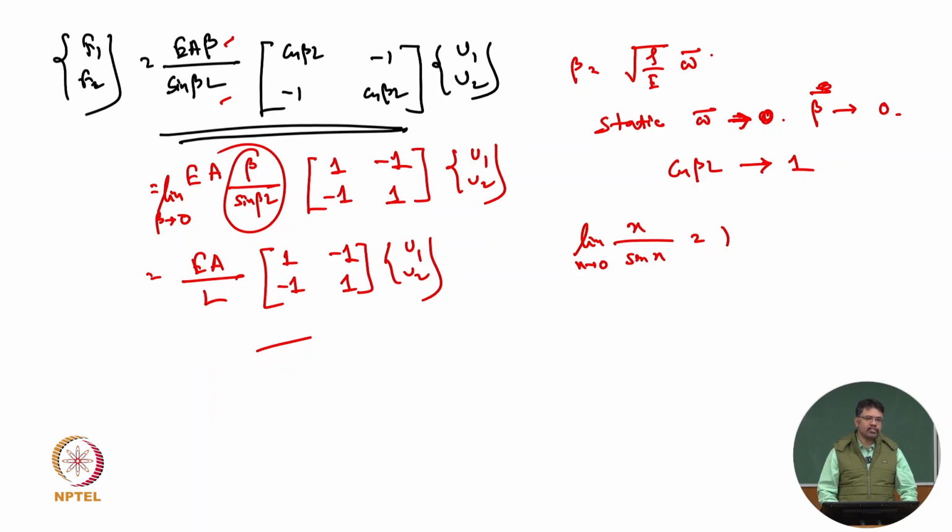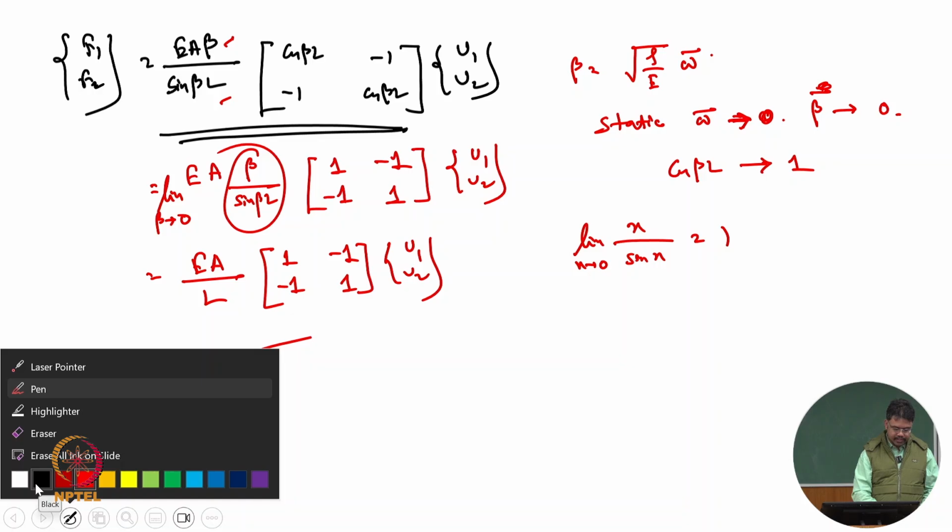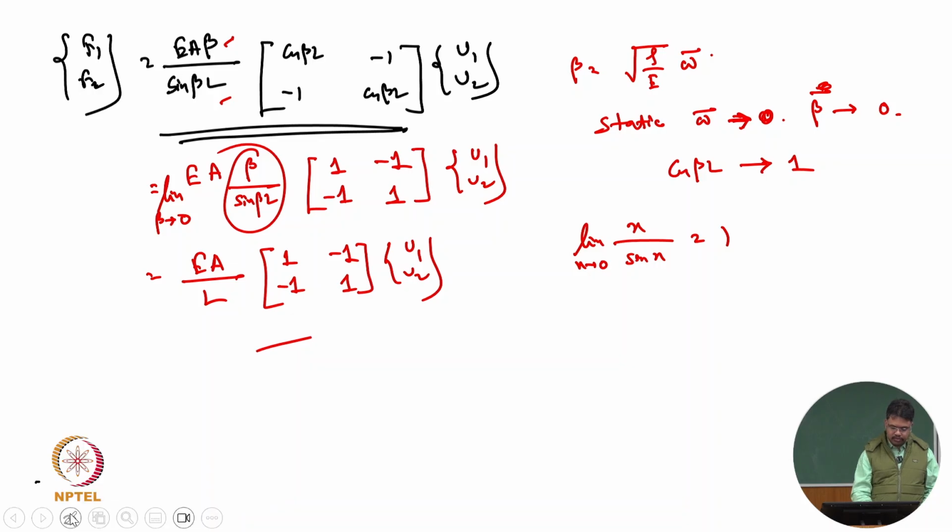For solving the natural frequency, we need what? Boundary conditions. So we need to put the boundary conditions here for solving the natural frequency. Suppose we are asking, let's solve for the bar having one side fixed or pinned, whatever, because that has only 1 degree of freedom. So one side is fixed or pinned, just to find out what the natural frequency of that bar is.